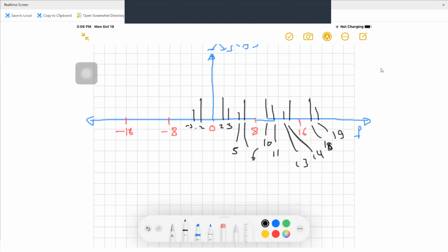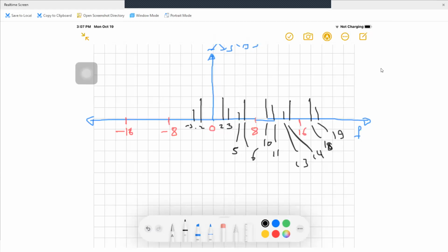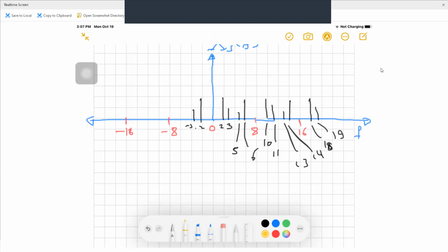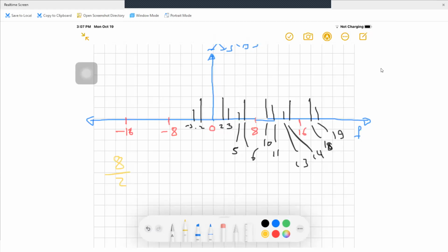Again, what will happen to the recovered signal? We are going to use a low pass filter with cutoff frequency equal to the sampling rate divided by 2. So it will be 8 divided by 2, and this represents the cutoff frequency FC. So FC will be 4 kilohertz. I'm going to plot the 4 kilo and the minus 4 kilo.